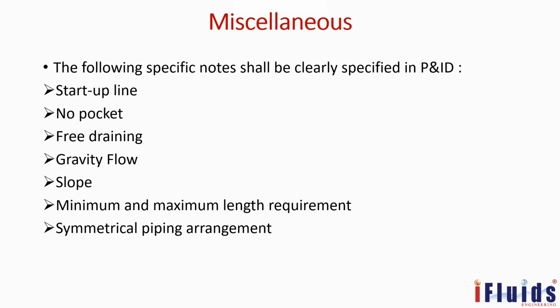Startup line. Sometimes some lines are used during startup only. In normal operation, these lines will be of no use. During the startup only, this will be used. That startup line we have to mention. Then no pocket. There should be no pocket in the steam line, so that a vapor trap or air trap should not be there.